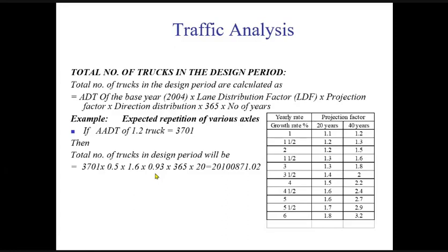Now, where is this 1.6? If the vehicle has a growth rate of 4.5%, then we take 1.6, or at 5%, we can also take this 1.6. So if you are designing for 20 years, then it is 1.6, and for 40 years, it will be 2.4.